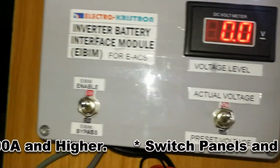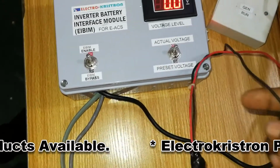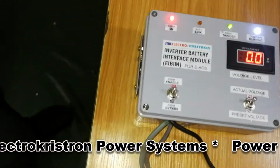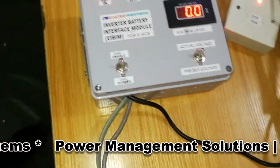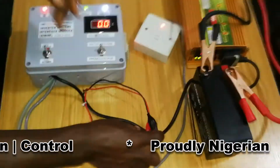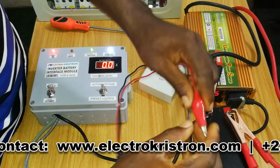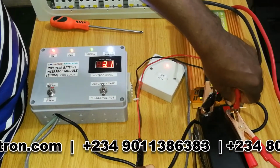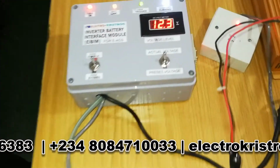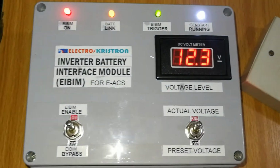Nothing is happening because the battery clips here have not been attached to the battery. They are meant to measure the actual battery voltage, but they are not measuring yet because no connection has been done. TJ, can you please help connect to the battery? Okay, there you are. So this is telling us right now that the voltage on the battery itself is 12.3. That's the essence of the actual.